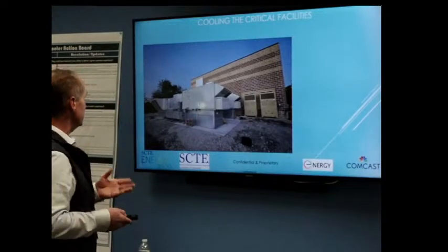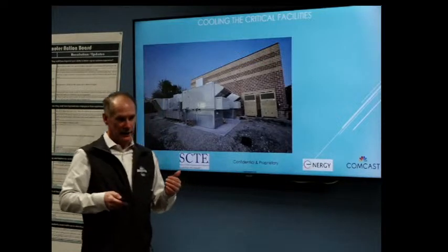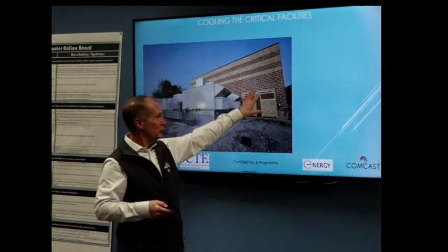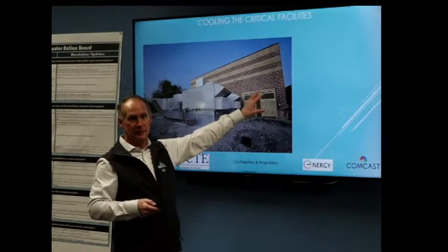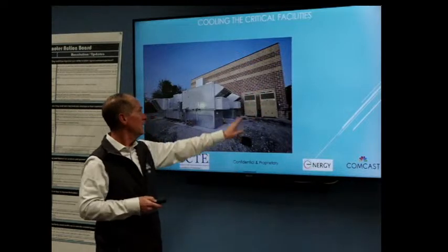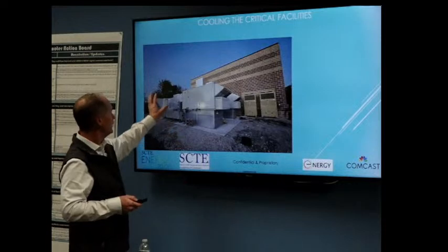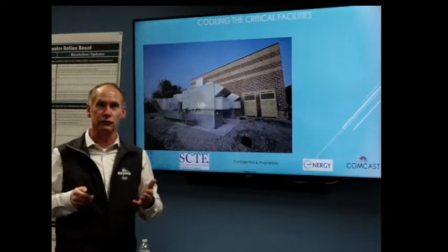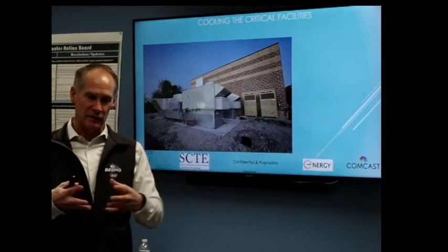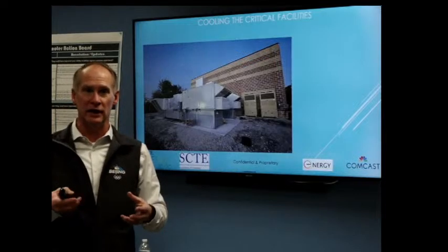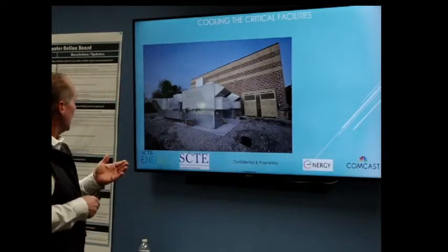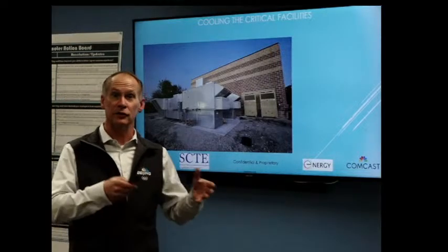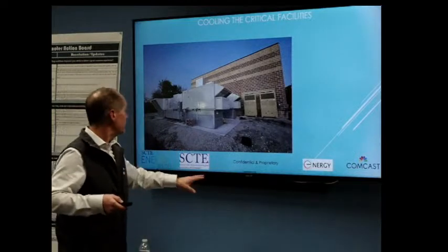The hybrid system itself takes care of a multitude of different cooling opportunities based on the buildings that we've got. You have a normal wall pack system that is a highly dense 10-ton system in an N+N relationship. And then you've got a package system which is based on RTU technology, rooftop unit technology, where it has everything self-contained in a packaged or skid type architecture. As your mechanical engineers or your critical infrastructure engineers are solutioning for the best solution for the building that they've got, this is a good solution.